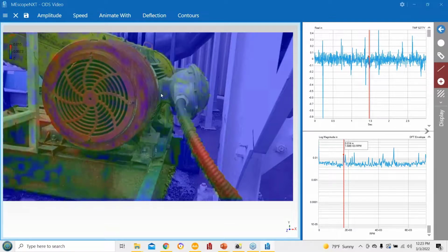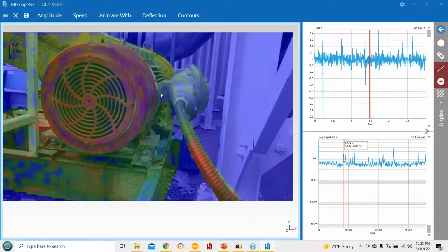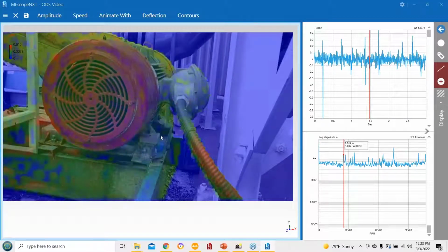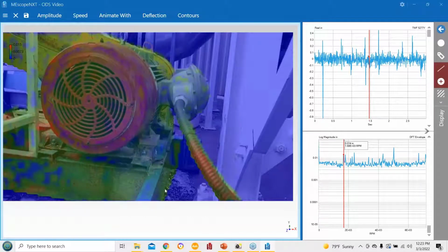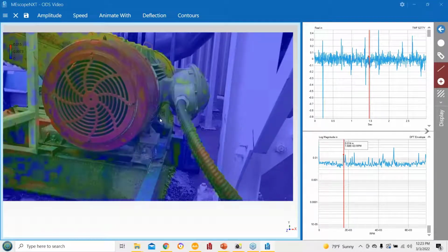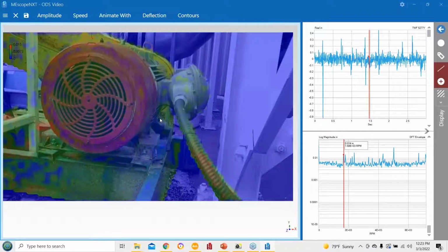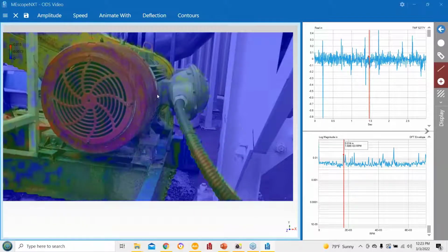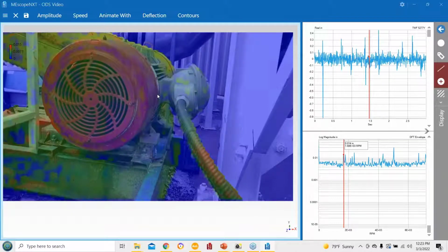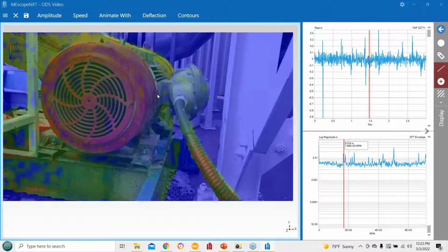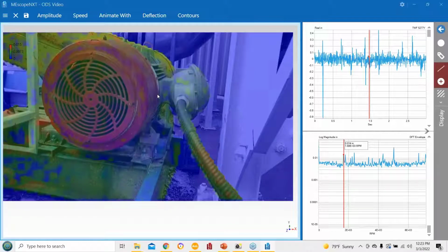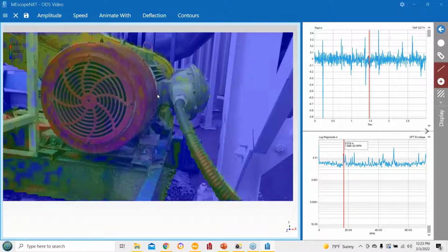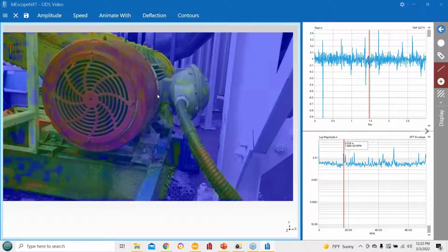But when you use that label command that we didn't go through, you could select some points and get a label and see exactly where you normally would take data. And that's going to be the future of trending. You might walk around with your iPad and take a video of a marker on the housing. So you're replacing your accelerometer with a sticker and a high-speed video, which should be very quick to take your data.